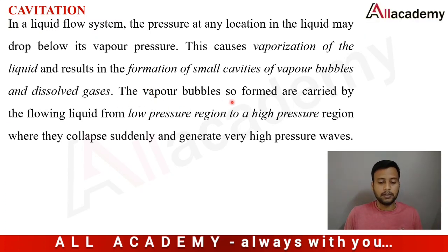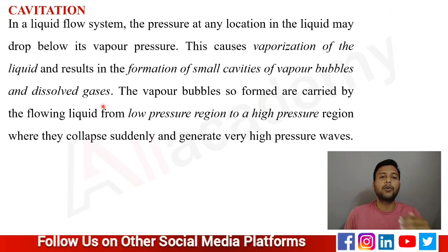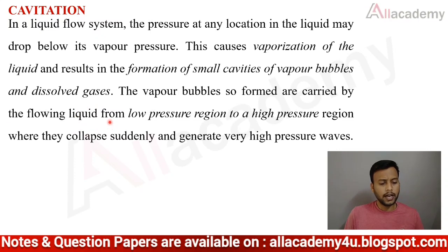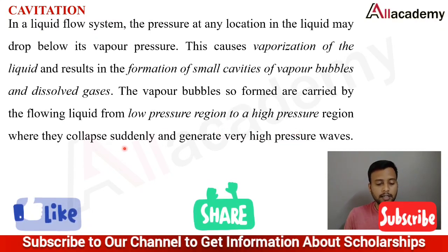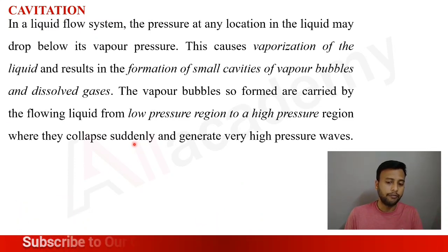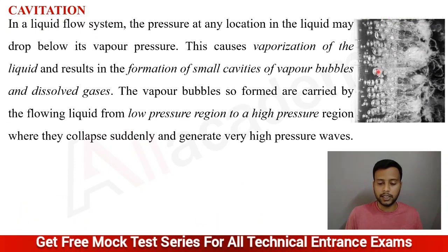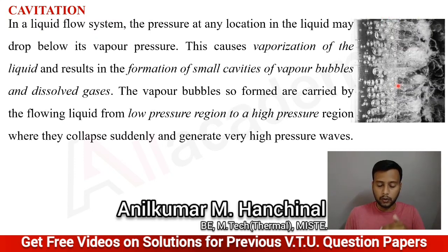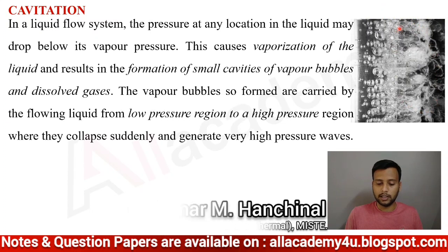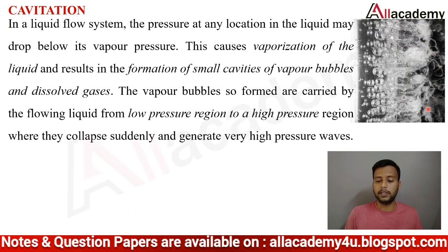Now the vapor bubbles so formed are carried by the flowing fluid; along with the flow, these vapor bubbles also flow with the fluid, from the low pressure region to the high pressure region, where they collapse suddenly and generate very high pressure waves. Here you can see these bubbles. They travel from the low pressure region to the high pressure region, and at the high pressure region they collapse suddenly and form the waves. You can see the high pressure waves here in this section.